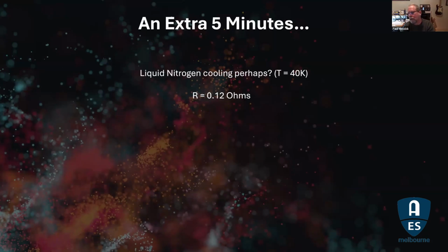So what if we cool this thing? T is one of those values there. So let's dip this thing into liquid nitrogen. Now, this isn't that much of a joke. I worked on a radio telescope where the optical stage did exactly this. It sat in a bath of liquid nitrogen and then had a little tiny, mouse-sized heat pump that would cool that optical stage down to 0.25 degrees Kelvin. It was at the time considered to be the coldest point in the universe.